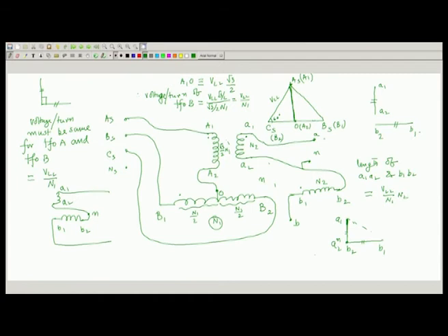These two transformers, in terms of number of turns, are not identical. Secondary turns must be the same, N2 and N2, but primary turns of transformer A, which I have just drawn vertically, differ. This vertical drawing has nothing to do with a real 90 degree axis; on the table you draw, I have drawn it so that I understand these phasors much more easily.